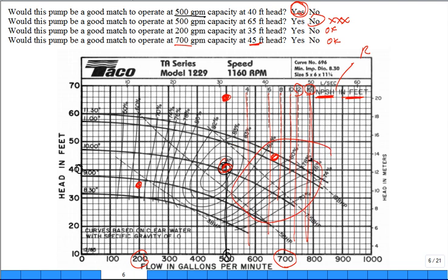You need a lot. You need more positive suction head available at the inlet to the pump. And if you wanted to, you could probably extrapolate and say, okay, if I just need 3 or 4 meters and I'm good. Or no, 3 or 4 feet of net positive suction head. Different manufacturers have different ways of displaying it, but it's always shown on their curves.